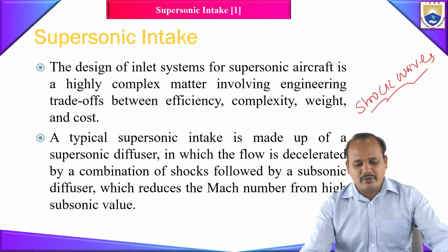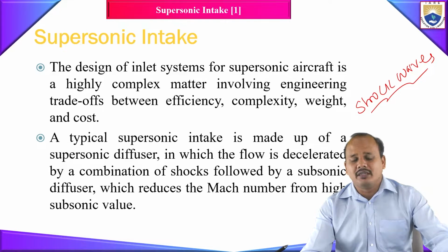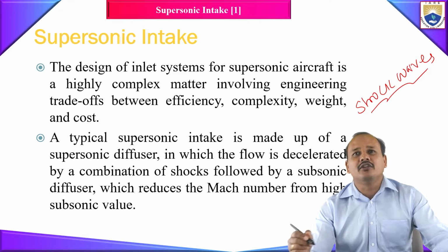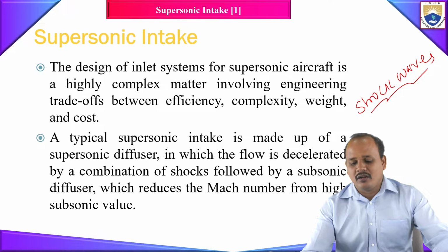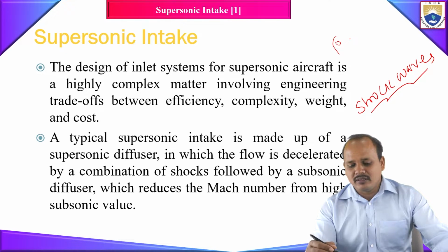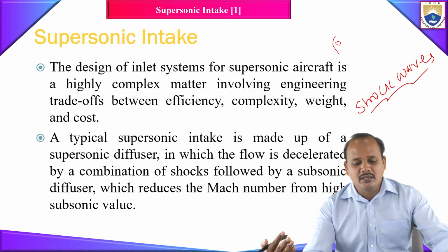You know what a shock wave is, right? Basically, it is the compression front formed in supersonic flow across which the flow properties jump. In the sense that there is a rapid variation in the flow properties, that is what we call a shock wave. A shock wave forms whenever the flow is supersonic and there is an obstacle present in that supersonic flow. Since our flight is supersonic, obviously there is going to be formation of shock waves in the supersonic intake.